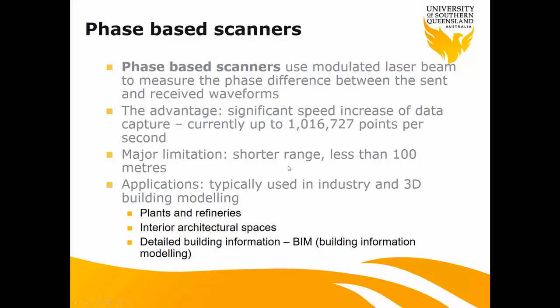But the disadvantage is that this kind of laser scanner usually has a short range, around or less than 100 meters. Just 100 meters, not 1 kilometer. So it is mainly used for 3D building modeling, indoor scanning, or short range work. For underground mining, that's okay, usually with a short range.